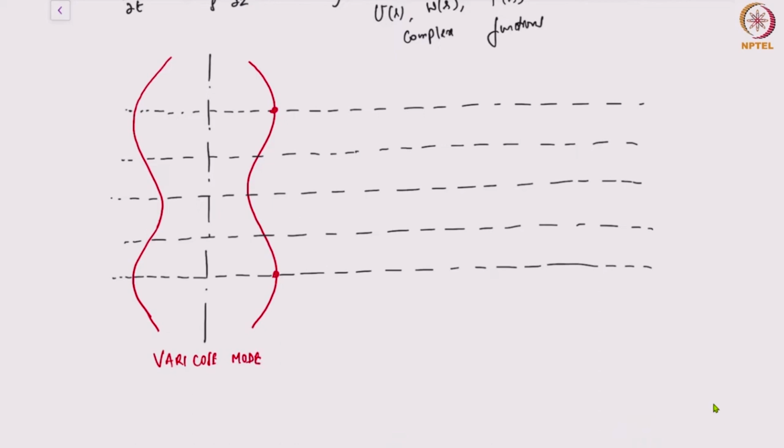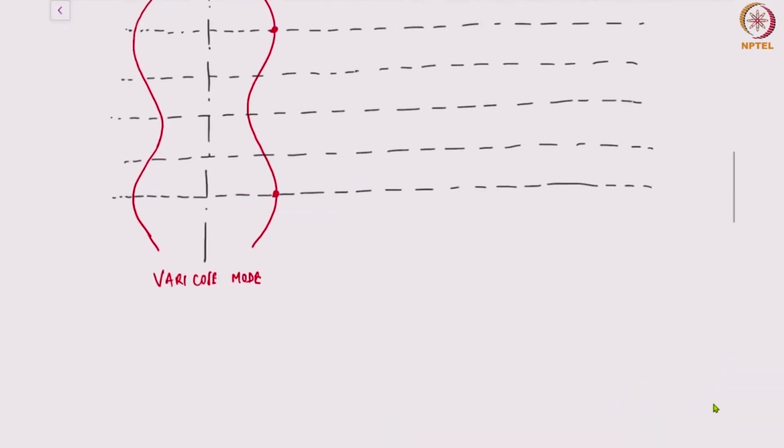Now let's basically draw the shape of the velocity field inside this filament. Let's first look at the streamlines. Let's assume that this is a filament which is bulging out, right? This is the state at which I have drawn. Remember, it's changing in time. So this is bulging out. Okay. So this is in a varicose mode in a bulging state.